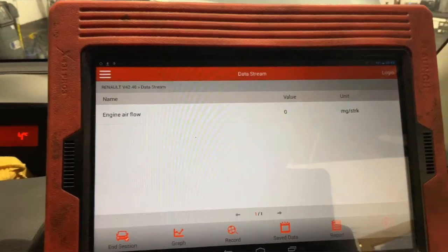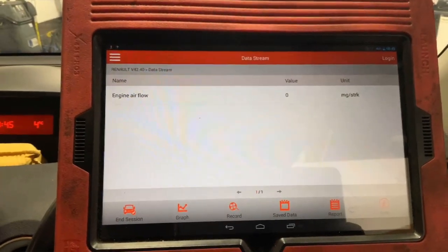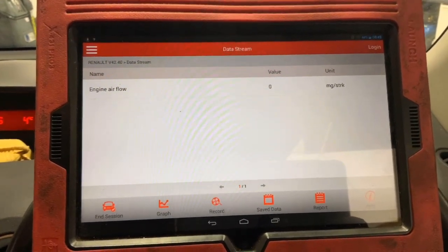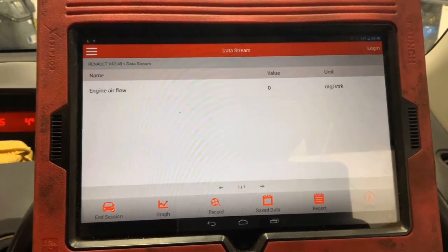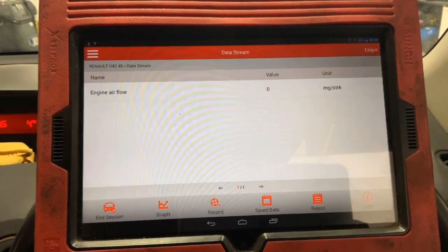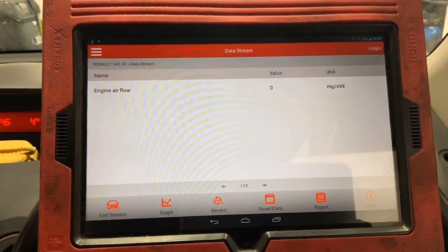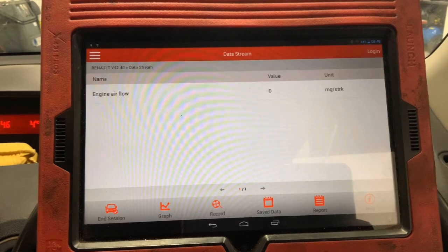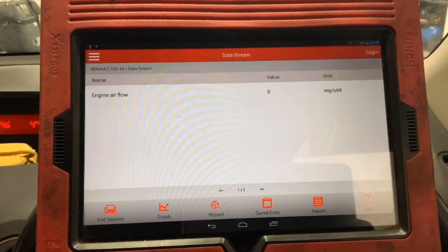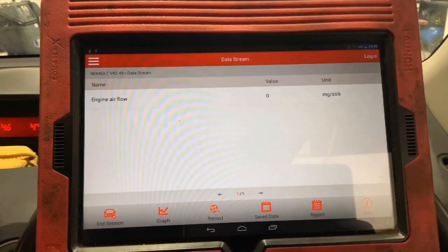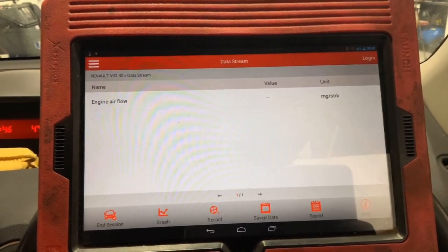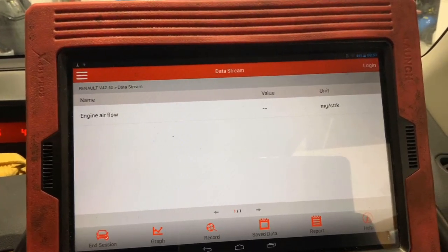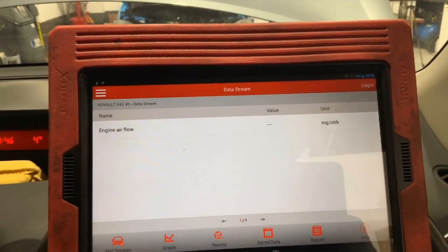So, oil contamination on an airflow meter. What could have caused that? There was a brand new air filter fitted to this vehicle. So my suspicion is that there's been an airflow fault previously with this vehicle and somebody's replaced the air filter. If the air filter that came out was heavily contaminated, that could cause oil to end up getting pulled back towards the air filter from the breather system. So this could have contaminated that airflow meter.